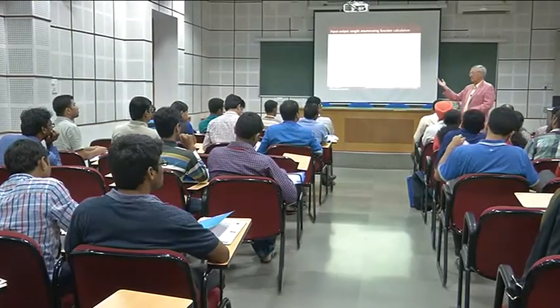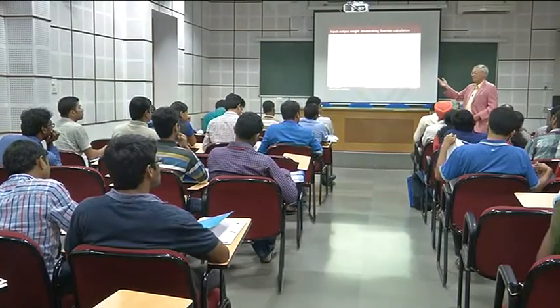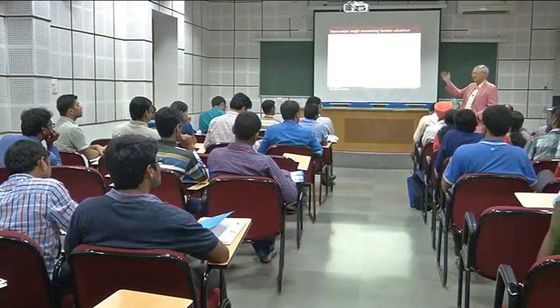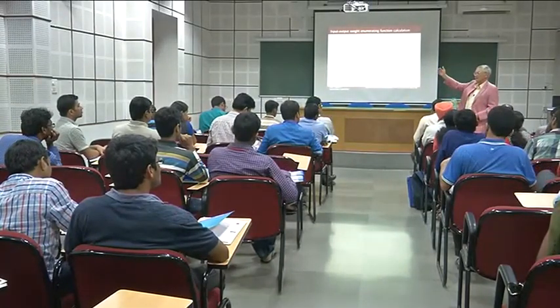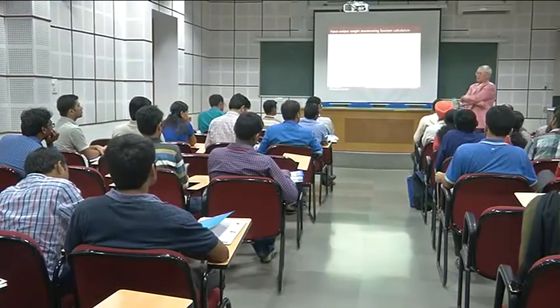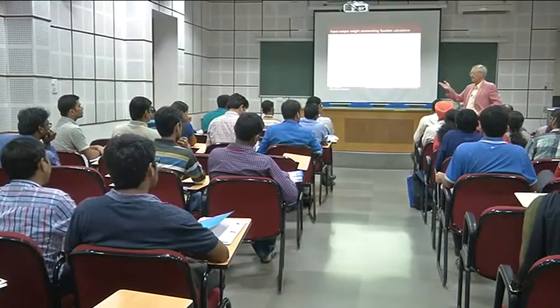So with the minimum free distance 5, there are channel error sequences of weight 3 that could cause an error. This could get you closer to the weight 5 code word than to the weight 0 code word. But they have to occur in certain positions, and it depends.